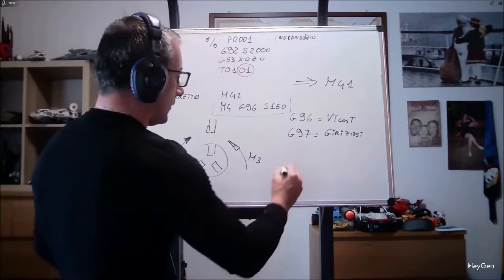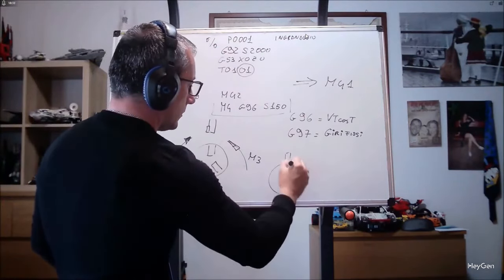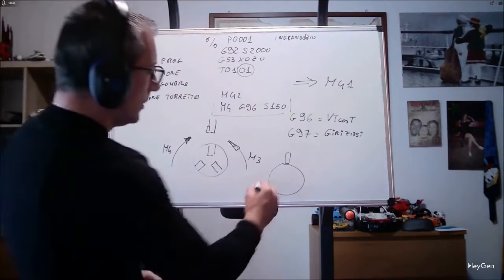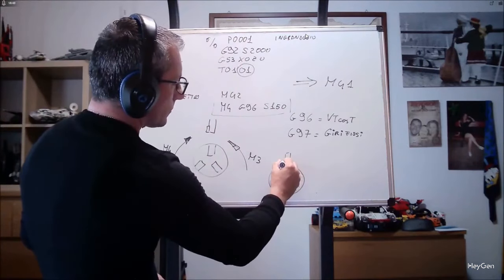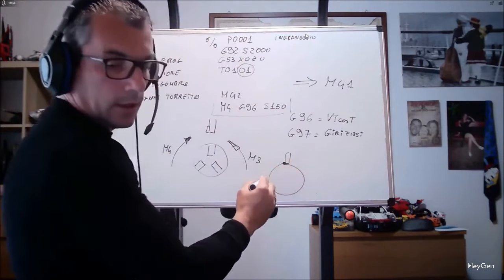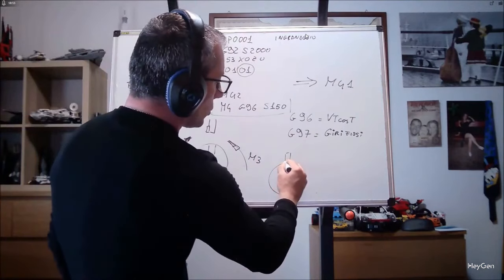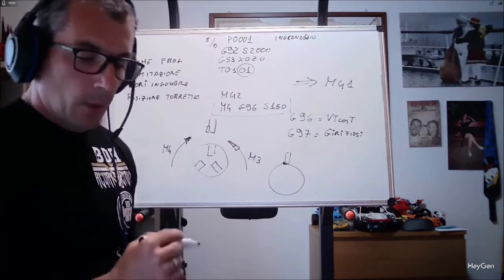What does this mean? If this, viewed from above, is my cutting insert, and this is my workpiece, in G96 at 150 meters per minute, the RPM of my self-centering chuck will be such that it will cover 150 meters of cutting for every minute of machining at the tool contact point. Okay.